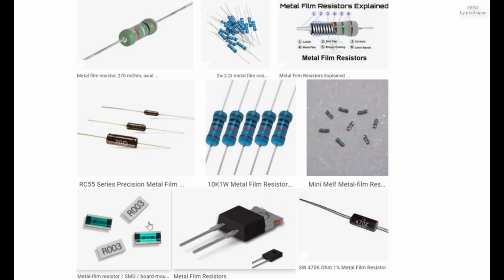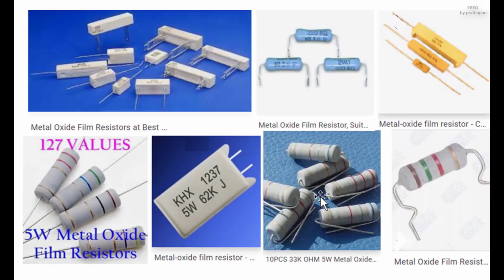The result is a reasonable tolerance, 0.5%, 1%, or 2%, and a temperature coefficient that is generally between 50 and 100 ppm/K. Metal film resistors possess good noise characteristics and low nonlinearity due to a low voltage coefficient. Also beneficial are their tight tolerance, low temperature coefficient and long-term stability. Metal oxide film. Metal oxide film resistors are made of metal oxides, which results in a higher operating temperature and greater stability and reliability than metal film. They are used in applications with high endurance demands.